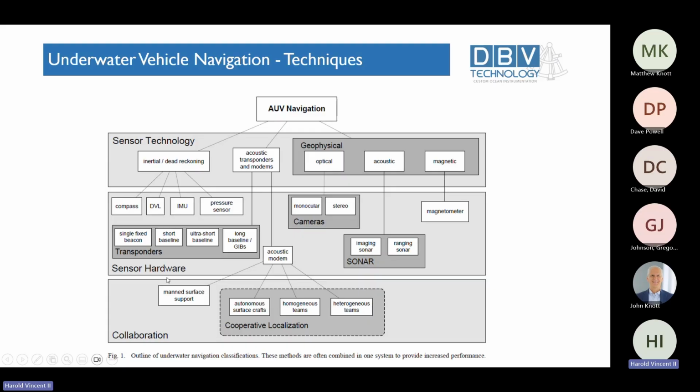In my terminology, I consider transponders and acoustic positioning systems to also be collaborative or cooperative, as opposed to other types of underwater acoustic positioning that might be performed in which it's uncooperative. You're just listening and trying to obtain the position of some underwater target. So in my terminology, I consider the use of transponders and transceivers in the various acoustic positioning modes to be a collaborative or cooperative means of acoustic positioning.